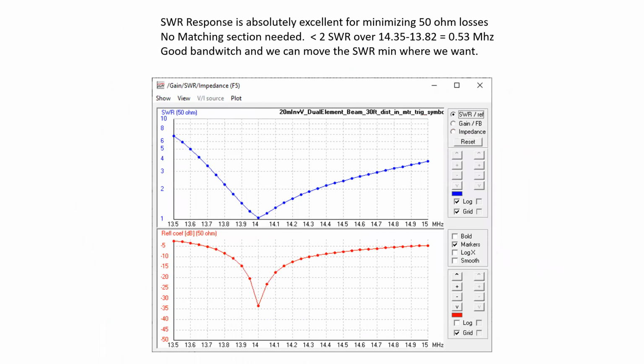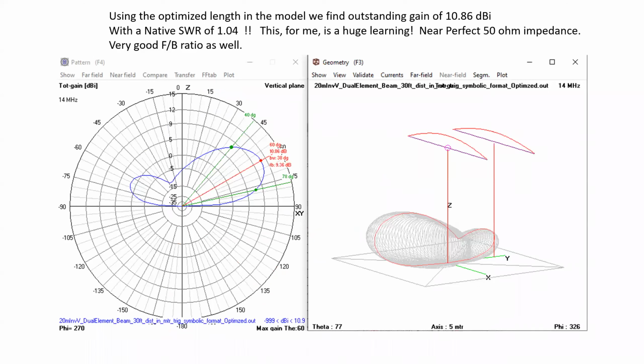Okay, good. The other thing, as long as we're talking about gain, I might just throw out a comment: if you model one of the dipoles that we've been modeling over ground in free space, the maximum lobe, of course, will be at 0 degrees, and the gain value you'll see will be much less, because it's now a full sphere as opposed to a half hemisphere.